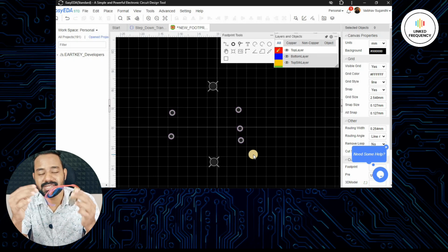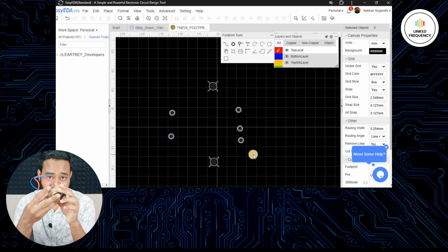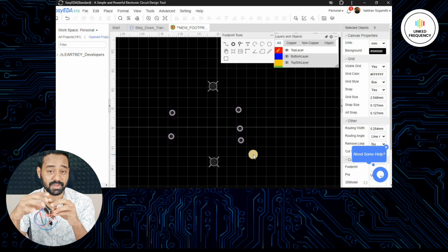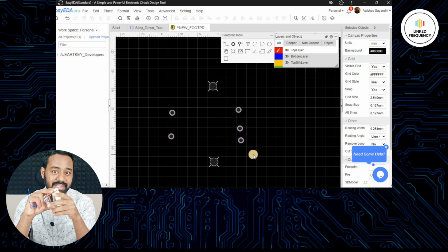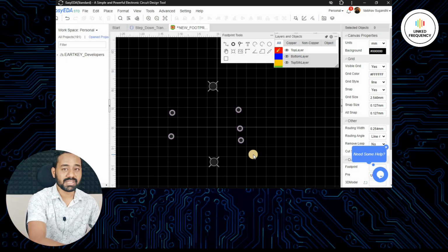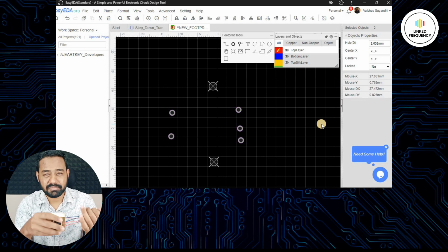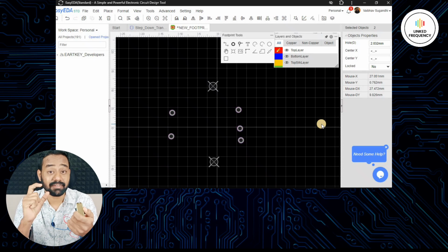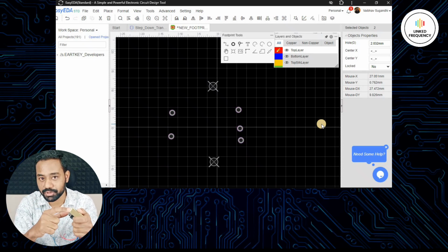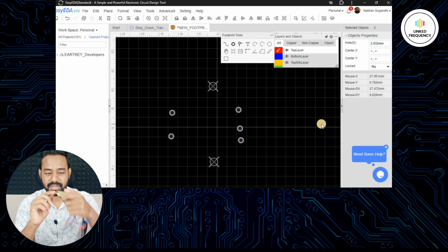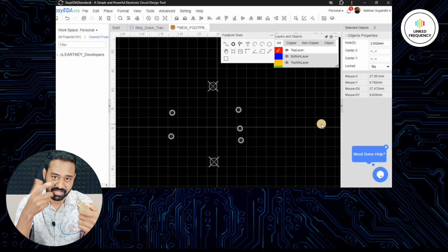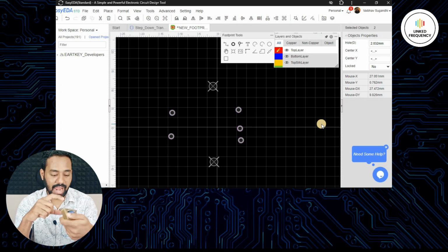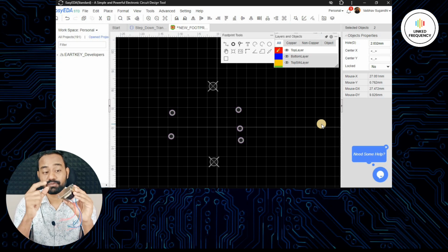Now it is time to measure the dimensions of the transformer in hand and use them for the design activity. As we already said, we do not have any specific datasheet for this transformer. That's why I'm using a scale to measure it. After measurement, we found that the mounting holes are placed approximately 70 mm apart. It has an oval kind of shape, so you can adjust it as per your convenience. So 70 mm is the mounting hole distance, and the total width of the transformer is 40 mm.